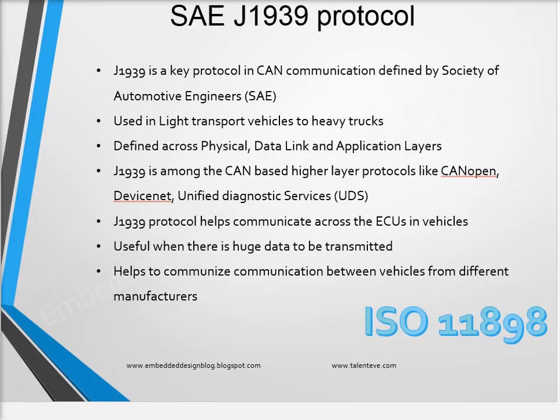So basically you have many number of protocols like that which are called the higher layer protocols, HLP. This J1939 is one among them. There are other protocols like CAN Open, DeviceNet, and Unified Diagnostic Services, which we call UDS.